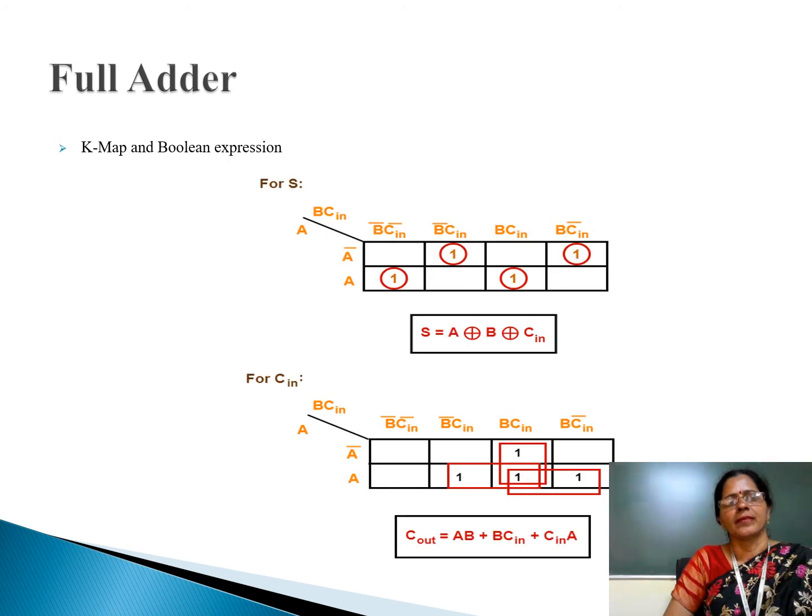Then next step, after writing the truth table, as per the basic fundamentals of the Karnaugh map system, we can convert the truth table to a K-map. How we put the truth table within the K-map, we can use that fundamental plotting of the K-map from the truth table and then use the simplification process.